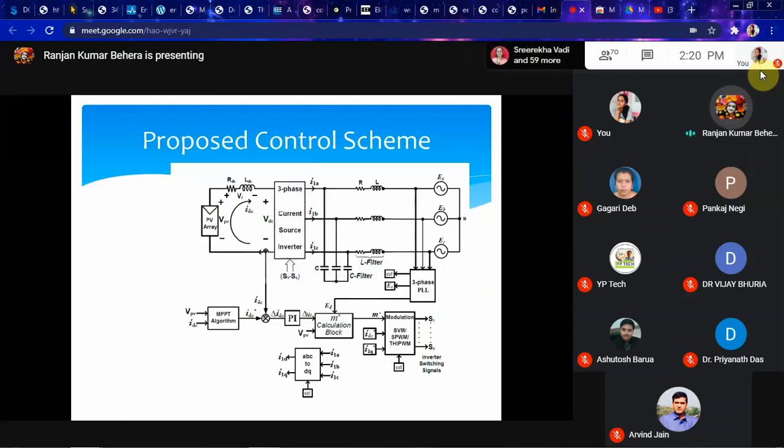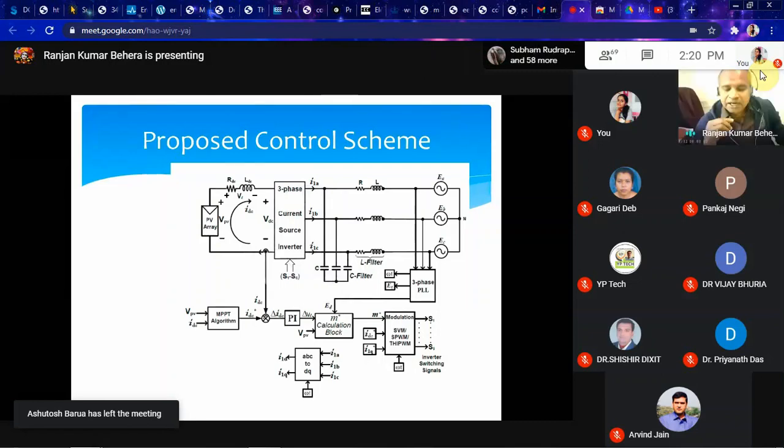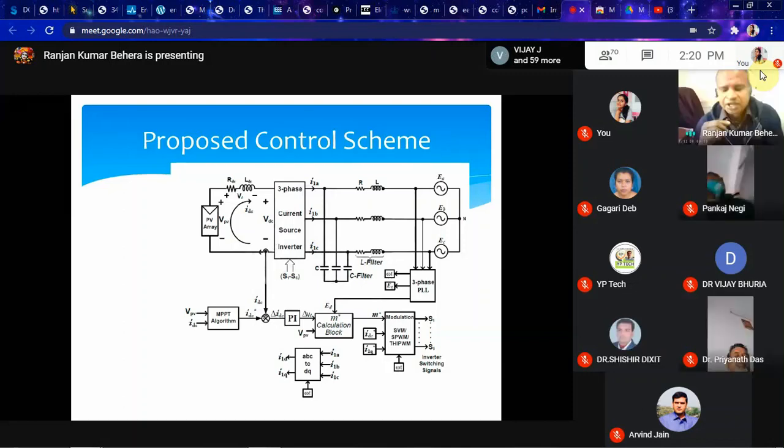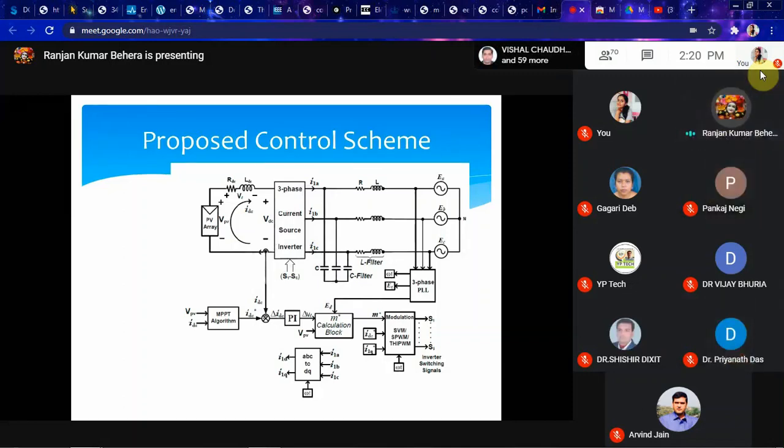And another one is constant. Second, this phase lock loop will ensure that if there is a constant phase shift, it will be maintained at the output also. So that means mainly we use this for full synchronization. So you get the information of the angle at which you want to inject the voltage. That is the most important thing, at which angle you want to inject the voltage. You get exactly that from the phase information.